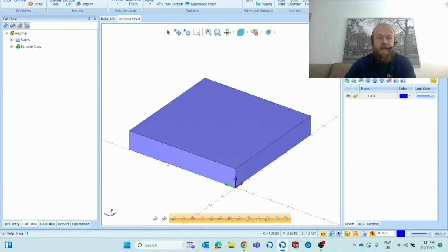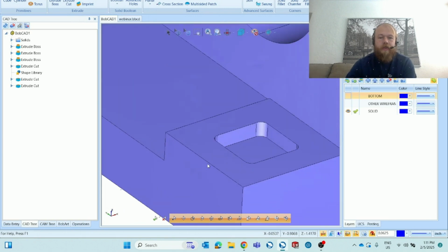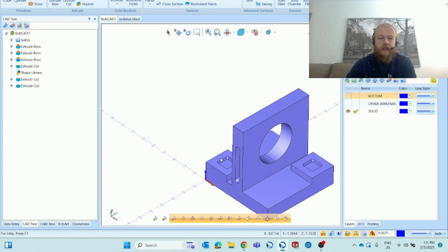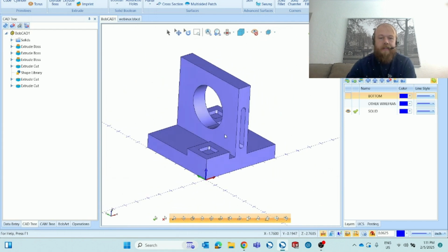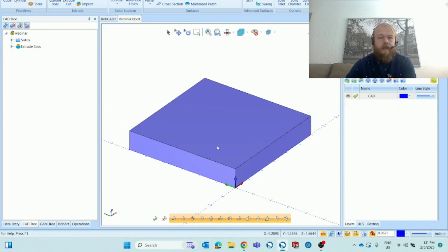We've made a 6-inch by 6-inch square, extruded it up 1 inch. Next, if we look at our final product that we're going for, we're going to do these 2 islands next on the corners. And I did that by sort of separating out the solid and the wireframe that I created on different layers.